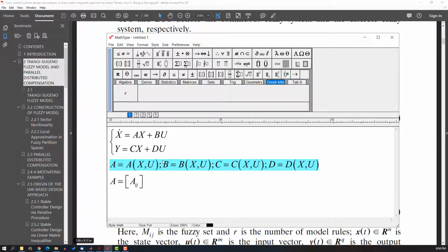So this matrix changes according to the state and according to the input; it is not a constant anymore. So from this, how can we design a controller? Because the state-space linear methodology is only for constant, time-invariant matrices, but not this one.